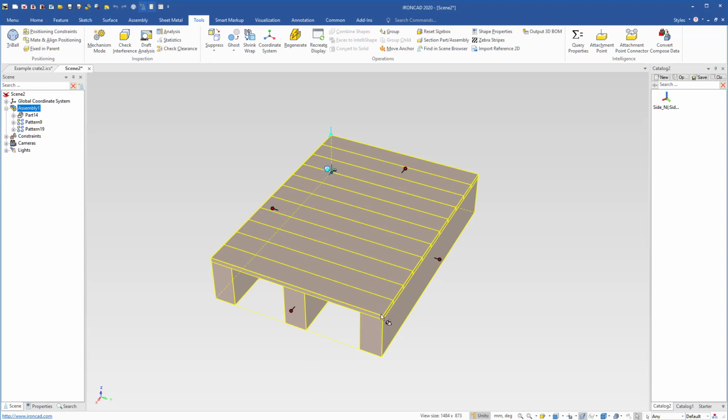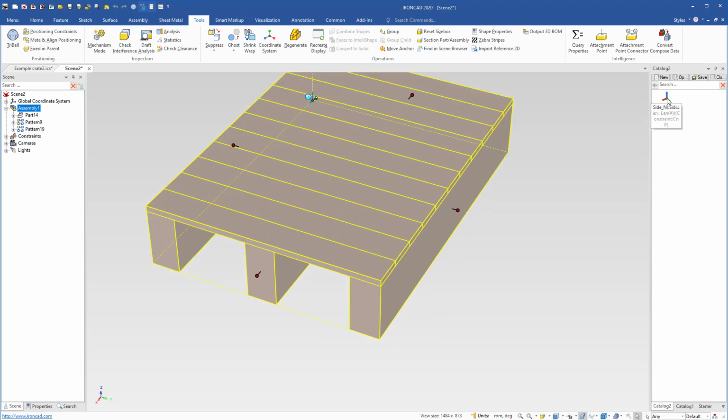So I can't add it to this corner because that corner doesn't move, another part will come in. We need to actually add it to the board that grows, which is this bottom board here, and then I'll just position it up into this point. So if we select our assembly, I can drag and drop out into this face, it doesn't matter where.